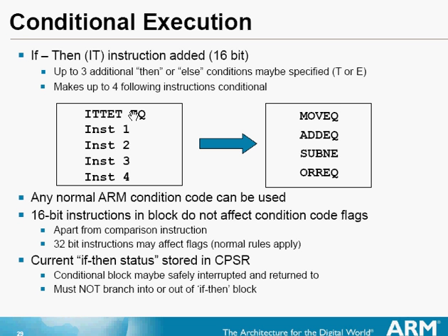But in Thumb-2, we have a new 16-bit if-then, IT, instruction for doing so. The 16-bit instruction looks like so. If it says equal condition, or the Z flag in PSR is true, then execute instruction 1, and 2, else execute instruction 3 and then execute instruction 4. This is what it says.